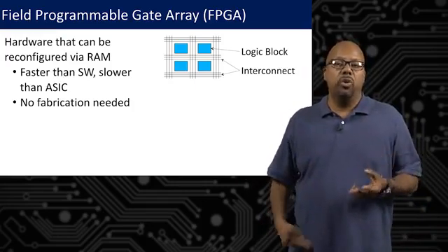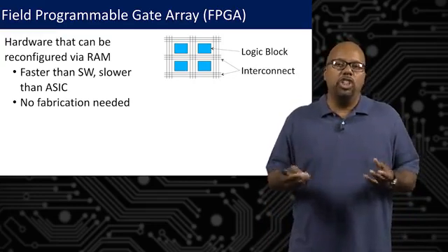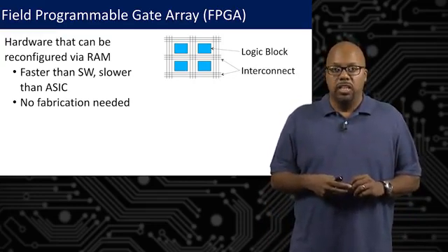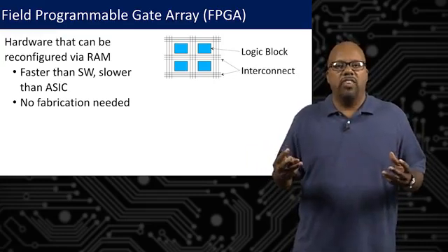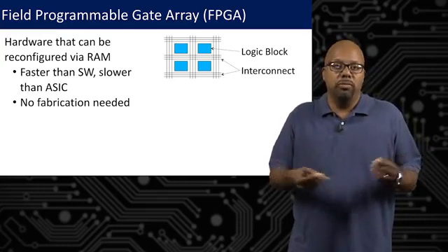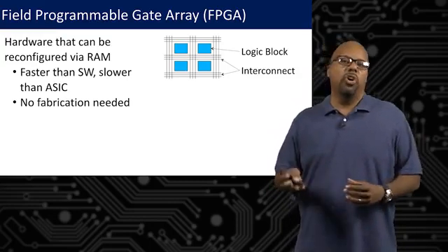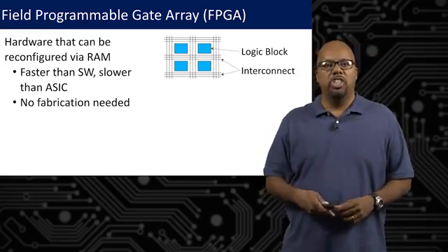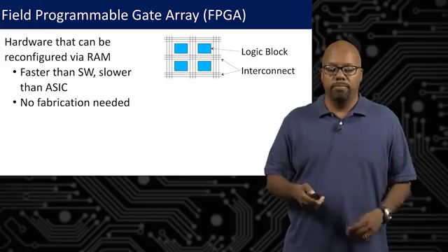See, when you make an IP core and you fabricate it as a chip, you have to manufacture chips, and that's expensive. So it only makes sense in high volume. With FPGAs, you don't have to fabricate. You just reconfigure it through programming. Just connect it by USB up to a computer, and you can rewire the thing. So that's much more convenient and cheaper. So if you have a one-off design, you would implement it in an FPGA over some sort of an IP core.